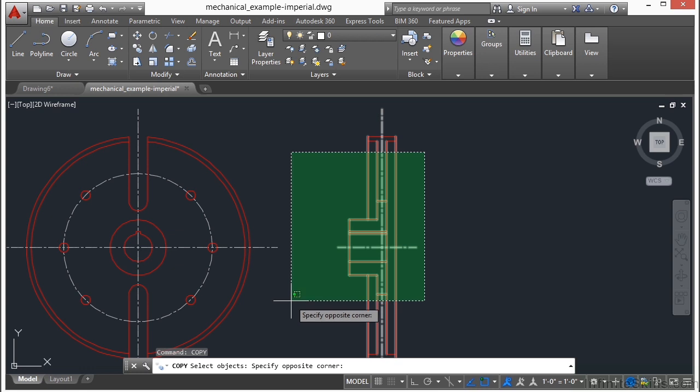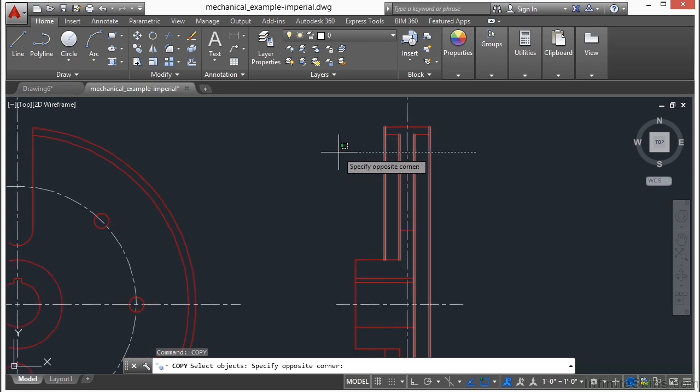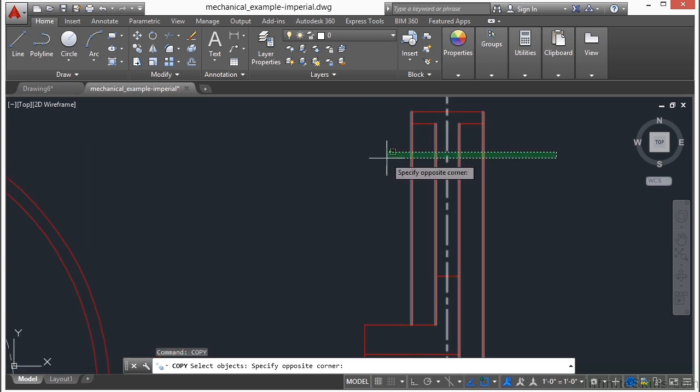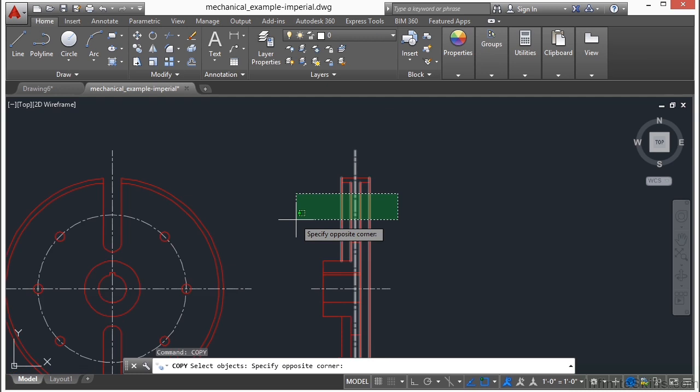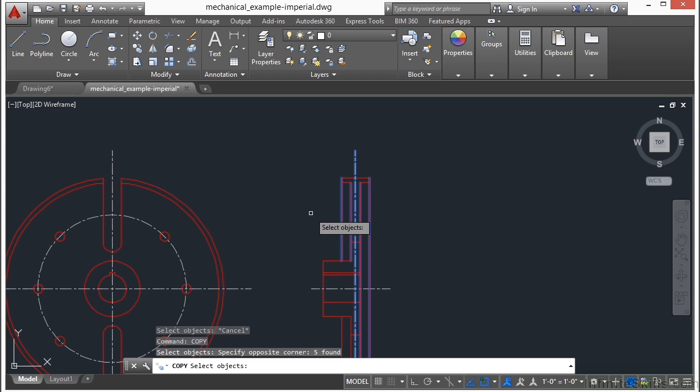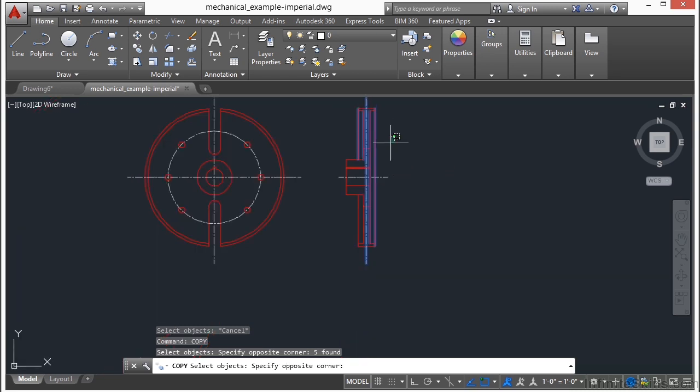You can see the very top part right up there. I'm going to zoom in a little bit. These items there at the top that are still red are not being selected, so they're not highlighted. So if I want to pass through something, I don't have to have this entire line selected inside my window, just part of it. Anything my window here crosses through will be selected. Left click again, and all of those items are picked. See, that's quite simple, very easy. Much easier than clicking on each one of these one at a time.